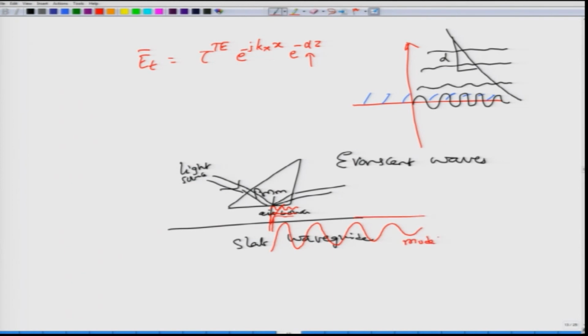So, it is just used to excite the mode inside a slab waveguide, and this form of coupling is known as prism coupling, which was very popular, and even now is quite popular to excite light into waveguides. So, the light that is being excited is actually in the form of this evanescent wave. Although we can show that the evanescent wave does not really carry any power in the direction perpendicular to the interface, it still can excite waves because it does not really go off to 0. What does go to 0 is the energy perpendicular to the direction of the propagation.